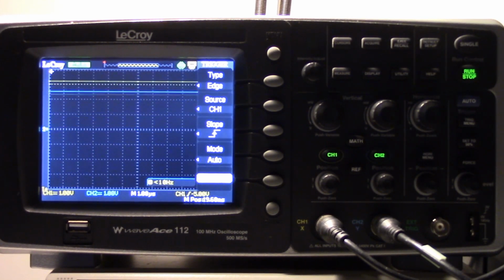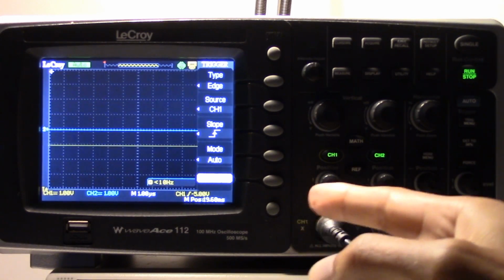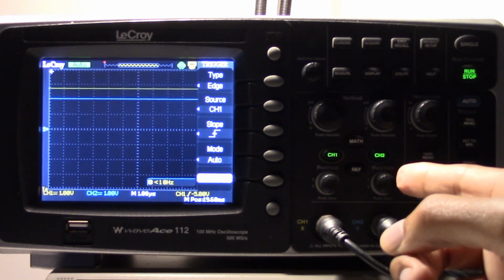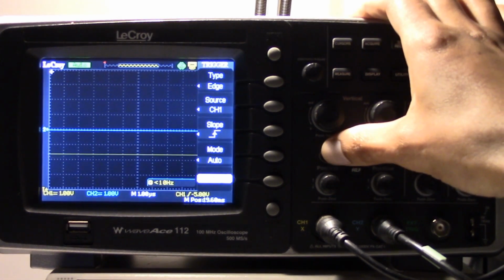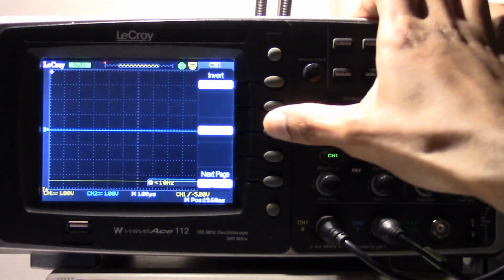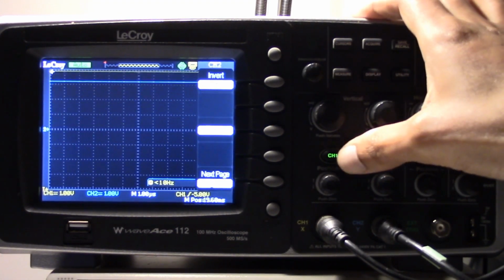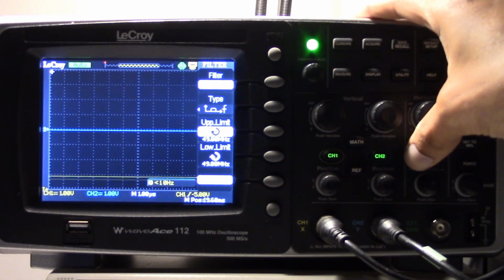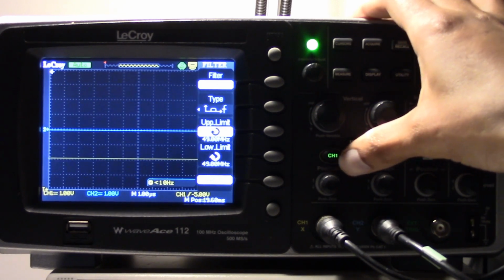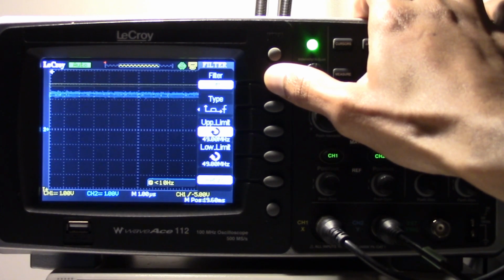So that's a check for how your trigger is set up. It's a check for how your circuit is set up with channel 1 and channel 2. And by the way, with channel 1 and channel 2, I am using some filters. That's how I have my filter set. It depends on how much noise you have. You may not have to use filters. It all depends. But I am using filters just to make that cleaner, because without the filter, it looks like that.